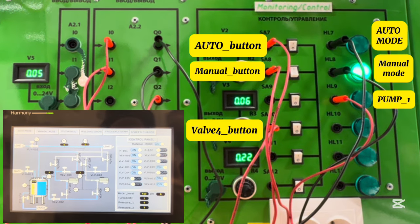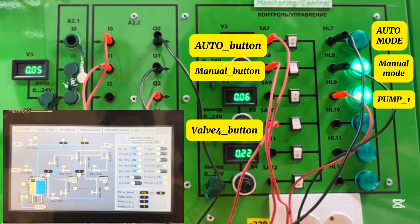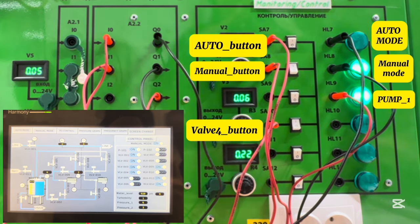On the HMI, we activate valve 2. When valve 2 opens, the controller automatically turns on pump 1, showing the logical link between them. Finally, we press valve 4 on the stand, which is used to return the sodium chloride solution back into the mixer.